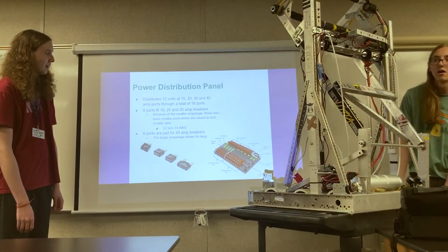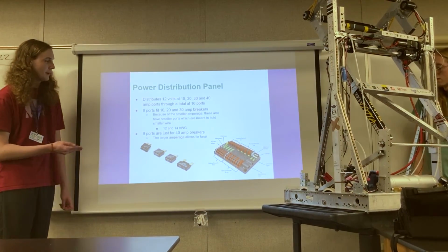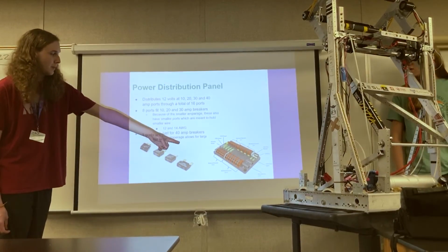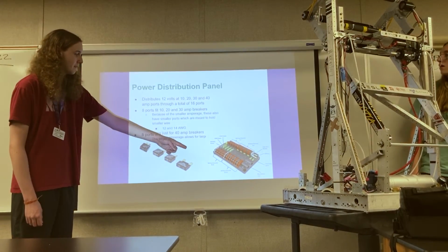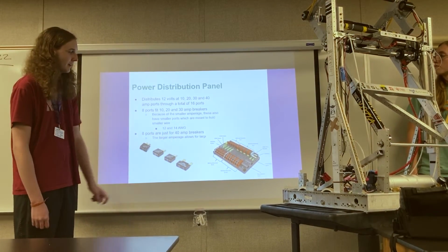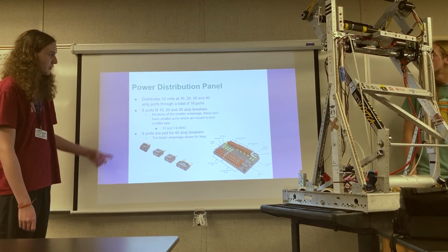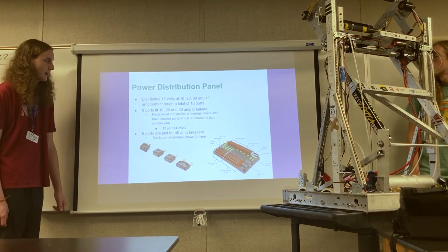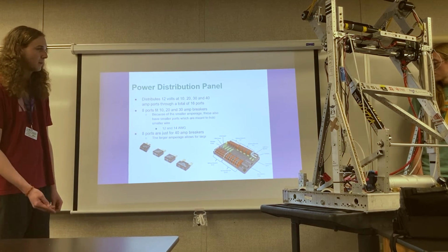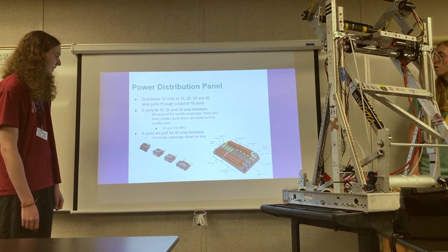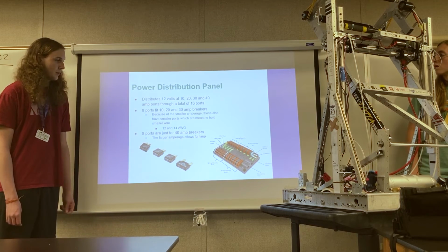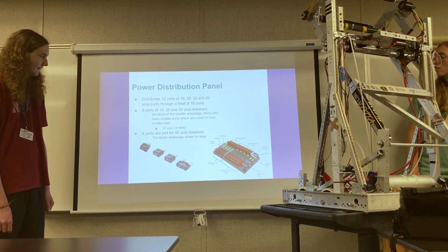Power distribution. Okay, so we were kind of talking about that earlier, but here's a diagram of it. That's where the power from the batteries feeds into, and then it distributes it to the various systems and regulates them to various degrees. They all have breakers, so that those trip hopefully before there's a fire. And yeah, the 12 and 14 gauge wire comes out of that.